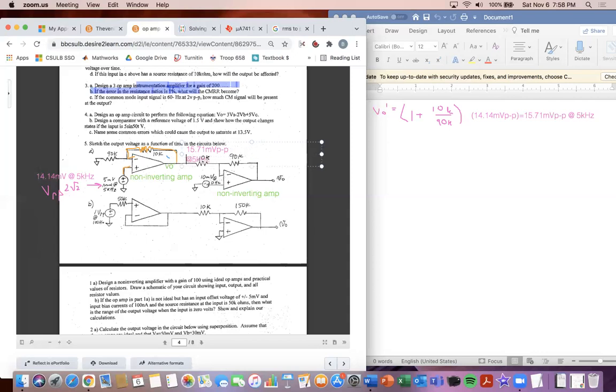Okay, we know that's going to be coming in at this output voltage. And then we have these 2 sources. So first, I'm going to look at this one right here. So I'm going to circle it and use superposition. First determine what impact this one has on the inverting amp. So pretend this source right here is set to 0 real quick. So let's look at that one. So the 10 millivolt source.